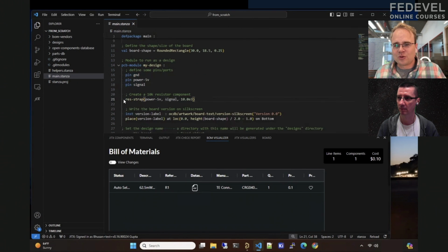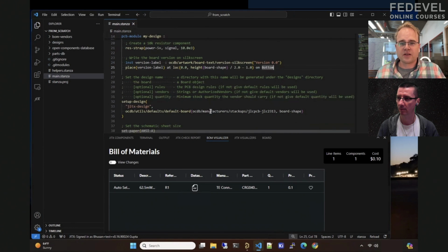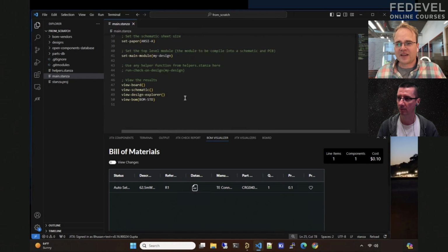And then there's two things. So I have this convenience function to add a resistor between those two ports. And that's a 10K resistor. And I also place a silkscreen label that's parametric. And that's it. So when I run the design, it's also choosing a stack up, and that stack up has materials. You set your schematic paper size and all that. Okay, so this is basically just a resistor and maybe like...